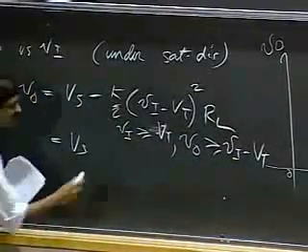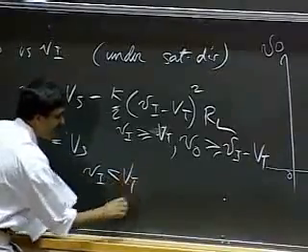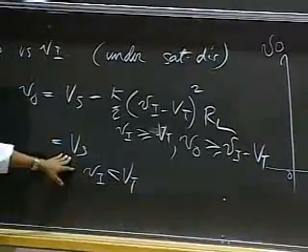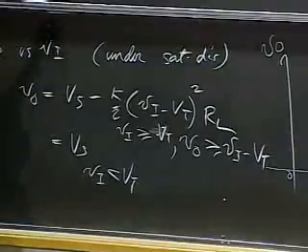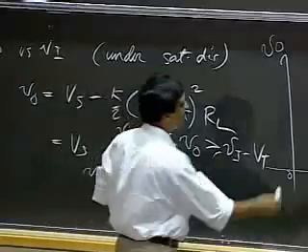And in our particular situation, when Vi was less than Vt, output would simply be Vs. Okay, if Vi is less than Vt, the MOSFET would turn off, and I would have no current flowing through RL, and Vs would appear at the output.